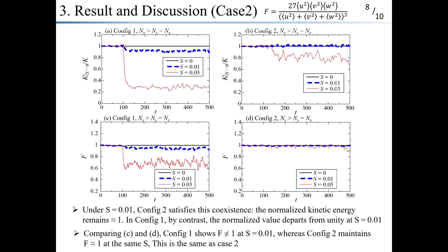At s equals 0.01, both setups show values near 1, meaning high entropy. At s equals 0.03, the previous setup's entropy drops significantly, while this study maintains values near 1, showing better entropy. This result demonstrates that even with only streamwise grid refinement, the modification in this study improved prediction of turbulent kinetic energy and isotropy compared to previous work.